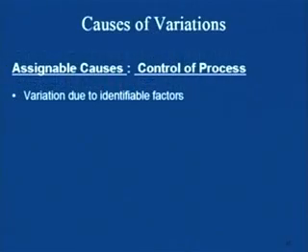As I mentioned, if you go for casting in the morning and in the afternoon or evening in the winter season, the temperature difference has an effect. If we combine the items of the morning session and evening session, the variation is clearly visible, and we can find the special reason for this. If we remove that special reason, the process becomes stable, or in control.